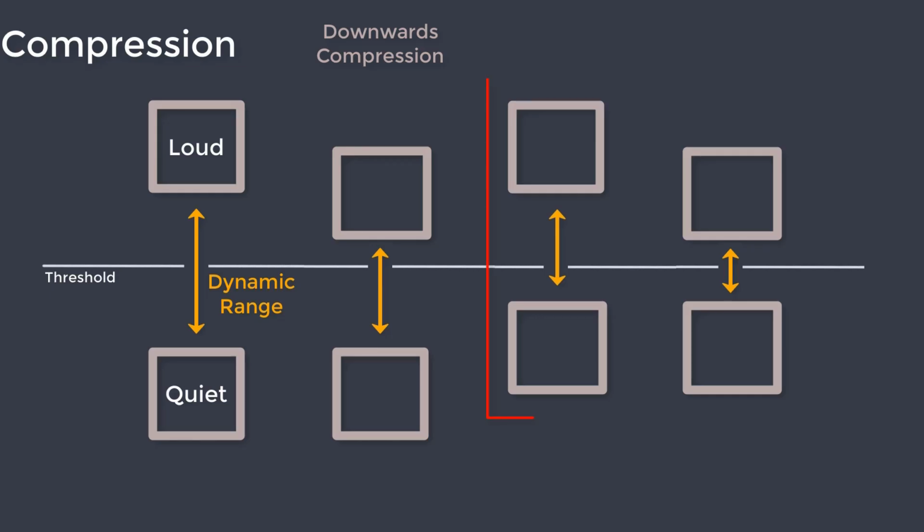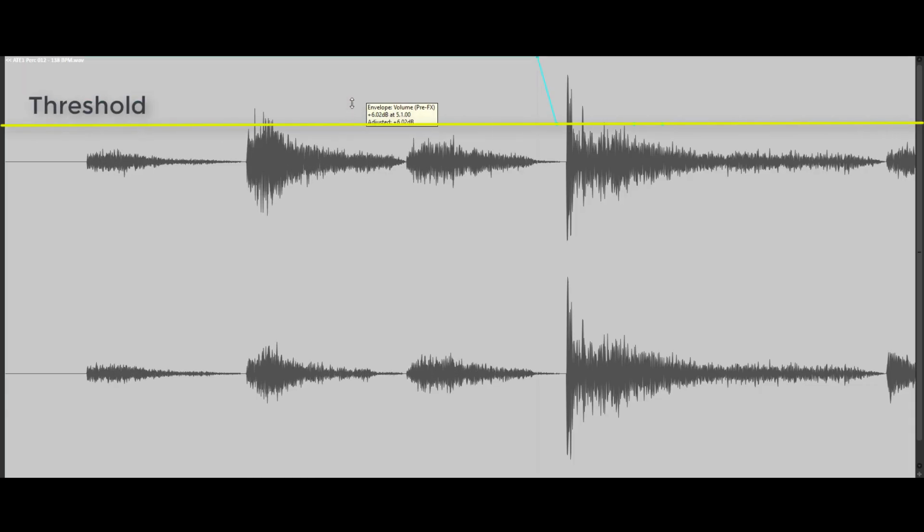Do we compress by pushing the lower signals up towards the threshold? It's upwards compression. Both ways reduce the dynamic range by the same amount, so why do we need upwards compression? As normal compression works on the louder parts of the signal, unwanted side effects like changed transients or pumping will be easily noticeable for the listener. Upwards compression, though, leaves the louder parts unaffected and can provide more loudness without causing any of these side effects.